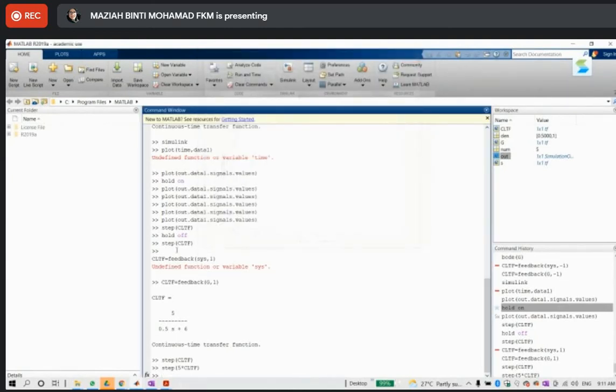Alright, just now when I showed you the closed loop transfer function feedback system, the value here is not -1, it should be 1, because the feedback here already represents negative. So you should use 1 for the closed loop transfer function feedback system. But if your feedback is positive, then only you put -1. So for a normal plus minus feedback, the constant here should be 1.